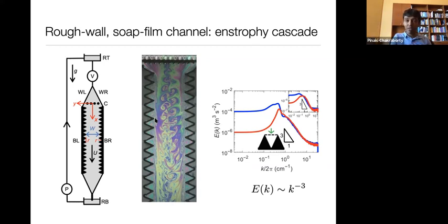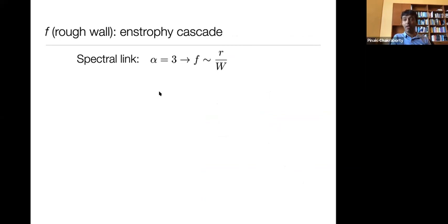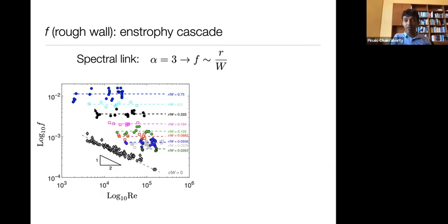With that, we can start to see what the Strickler scaling, or the rough scaling, is going to look like. Here is our data in this asymptotic regime: log of friction against log of Reynolds number. Here is the smooth data for reference. We did experiments with channels of various roughness values, and we see that you get to an asymptotic regime where the friction is independent of Reynolds number. But of course, the value in this asymptotic regime does depend on what the roughness is.